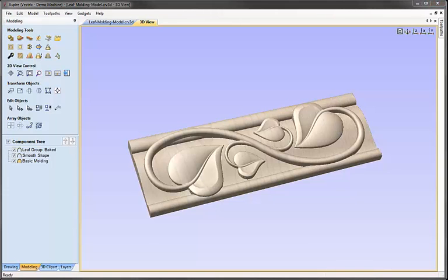We started with the vectors we'd created in the first section of this example. We then use the 2-rail sweep tool in order to make our basic moulding shape, create shape to build the leaf, and the extrude function in order to make our stalk. We then took a copy of the leaf and stalk and made the smaller version of the leaf and cropped out the area we didn't need before mirroring that whole part across the centre of the job in order to create the symmetrical design that we can see on the example.